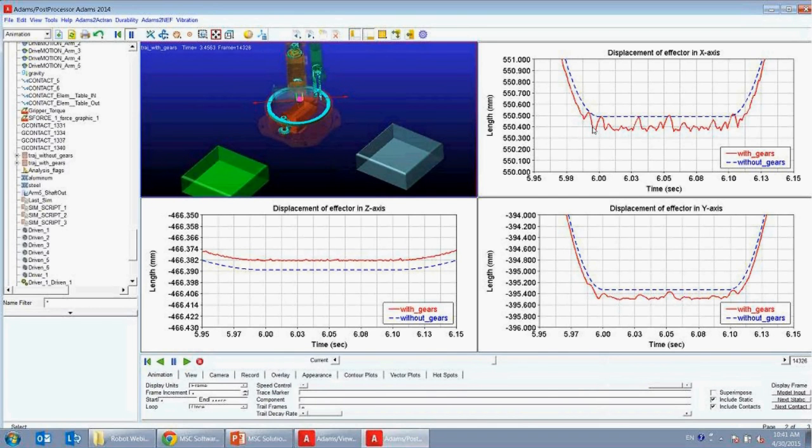You can observe a lot of back and forth vibration caused by the gear rattle effect that will be affecting the final movement. It's not a big deal if you are just moving or placing that object. It's probably not as big a deal with picking the object as it would be if you are manufacturing or machining that object.